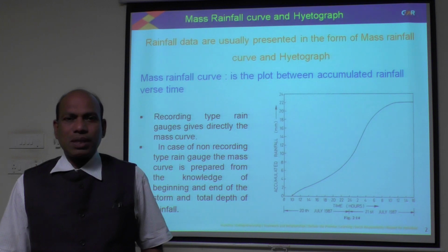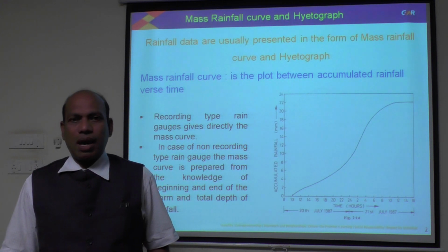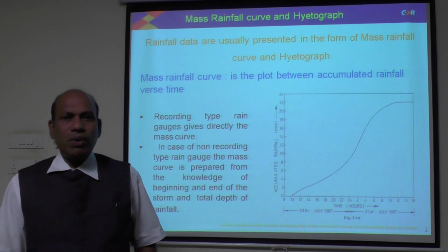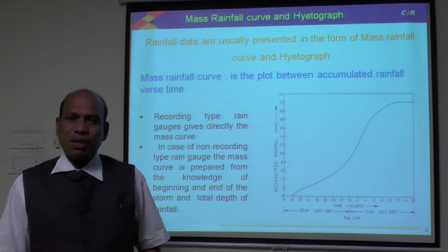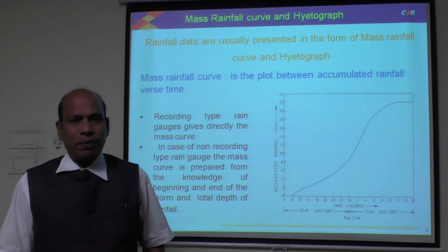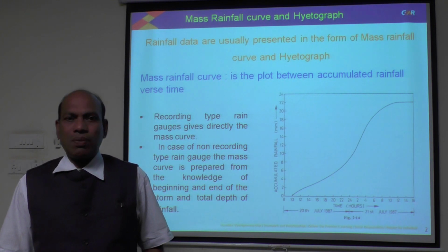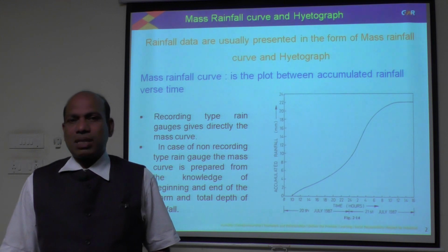Now we are going to discuss the mass rainfall curve and hyetograph. Why are we going to discuss these two? The mass rainfall curve as well as the hyetograph are used when we discuss infiltration studies and hydrograph analysis.